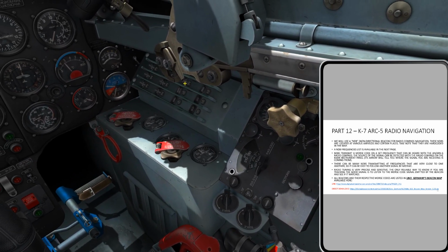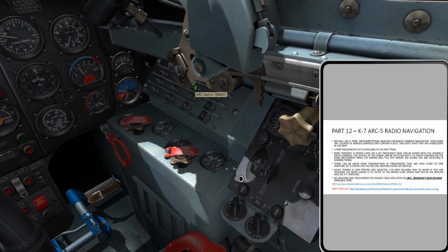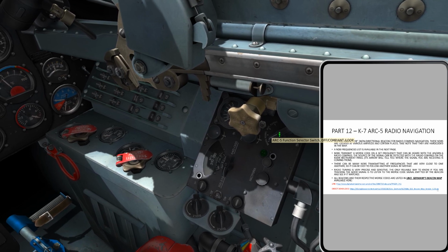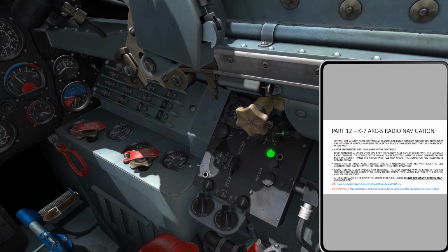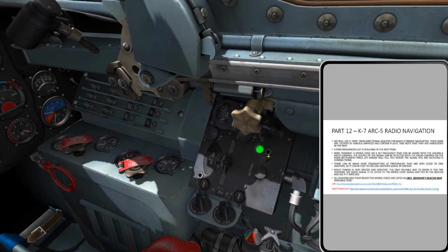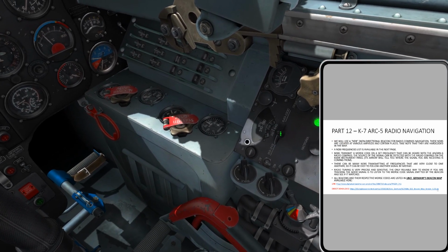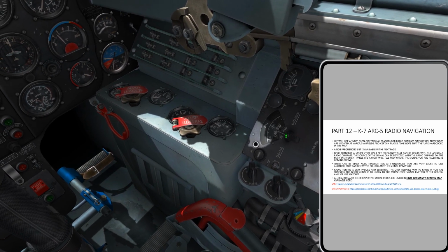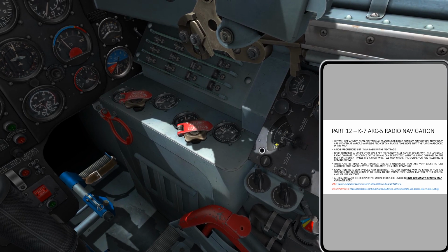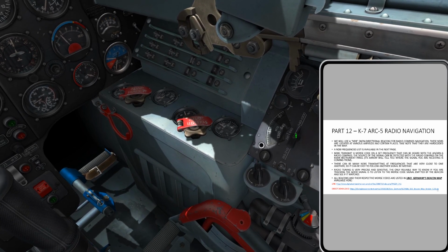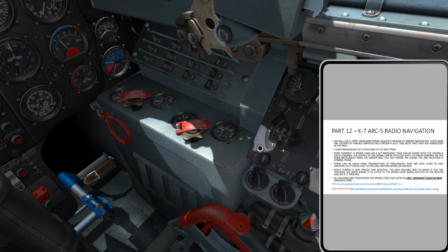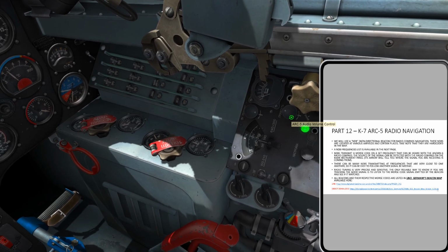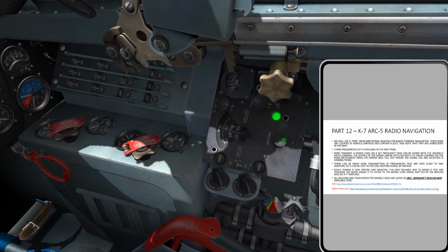Now the main switch is on up here, so I need to go on this switch, off compass antenna loop. Okay, I start out in the antenna position, and now I just need to select the right frequency range. So I wanted 443, so I need to go to the 310 through 640 range. Okay, I see it. It has like a little scale here, and then depending on the position of the switch, it has the corresponding scale. Now to tune it. Okay, to tune, it is this one. That's a volume control, scale light, tuning.